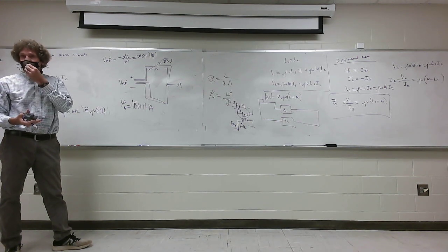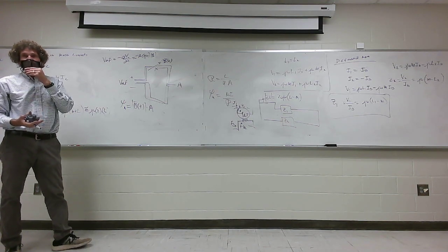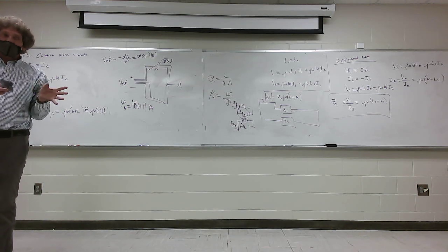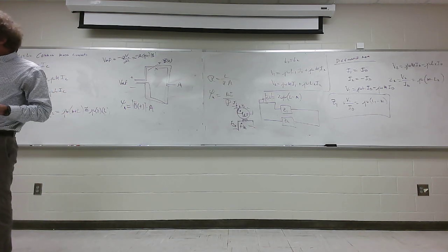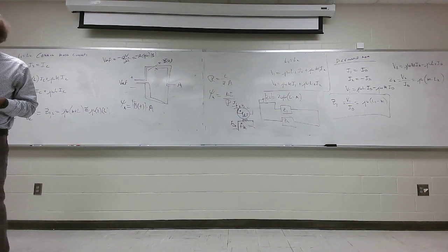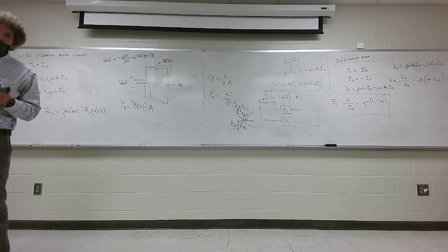There are other methods for common mode current to get into a system. And you probably see this fully. But when you start building stuff and putting it into an actual system that has to plug into that wall, common mode currents come from that wall outlet. First of all, anything coming out of that wall outlet has to go back into it, hopefully, right? Well, that's not always the case, and that's where common mode comes in.